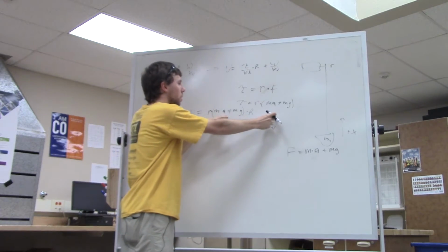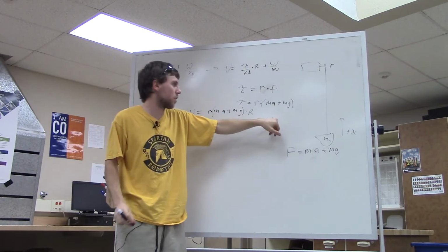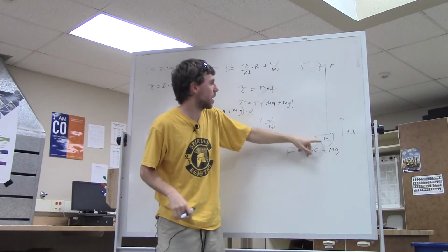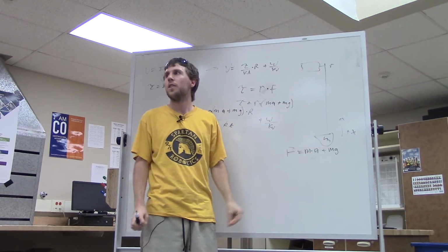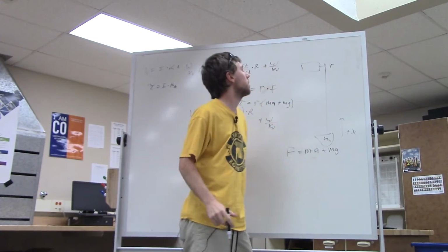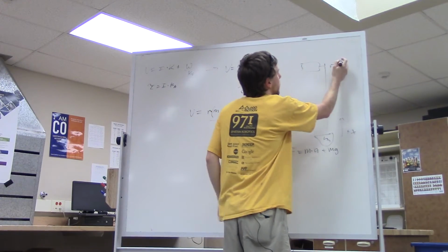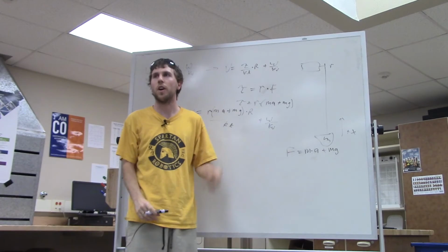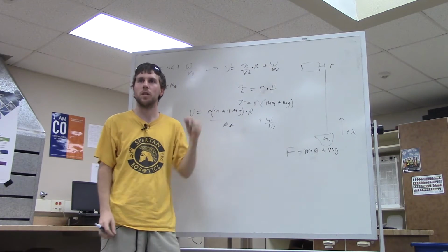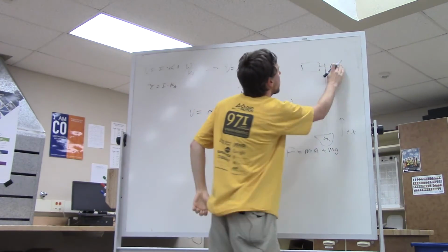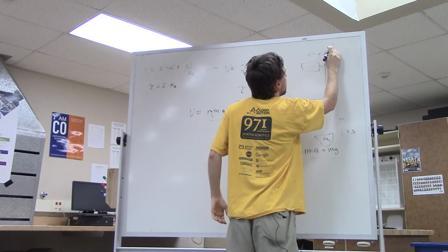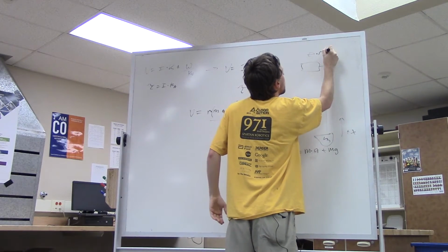Now what we need to do is relate the acceleration to the angular velocity of the motor. What I like to do is get everything in terms of the x coordinate here, so we're all talking about linear units. So we have the angle of the motor that it's spun so far. If we're in radians, 1 revolution is 2 pi. So 2 pi times the radius will get you the distance the surface traveled. So theta times r equals x.